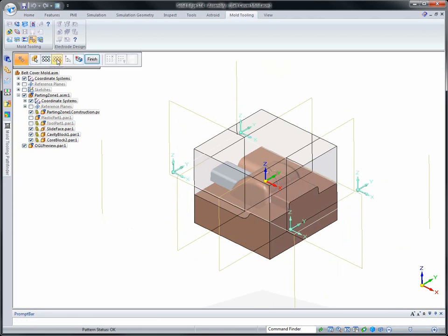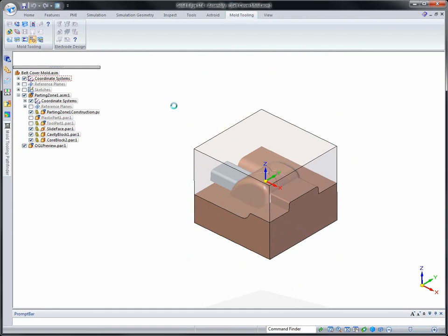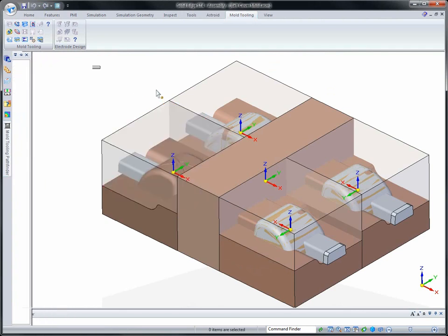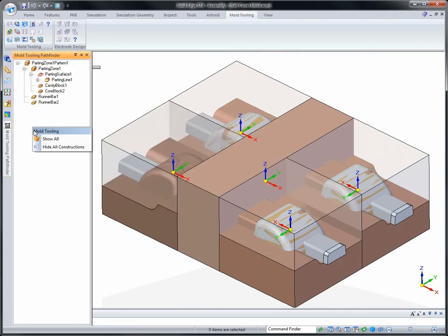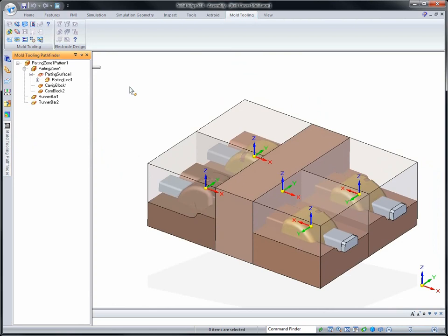And in this case too, I want to include rotating 2 of the cavities, core cavity sets, because of those slides. I have to be able to get the slide in and out. So they'll be 180 degrees off from the original. And then also want to define a runner bar, because I've built in pinch, what we call pinch in the mold, so that when the mold comes together, the plates don't hit. The core and cavity actually is the only thing that hits to make the seal. And there you can see we have our core cavity sets, and we'll just hide the construction geometry.